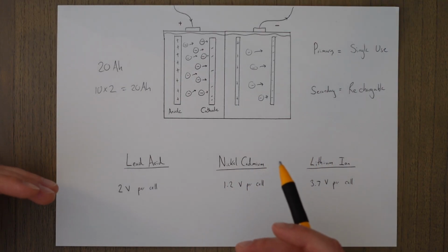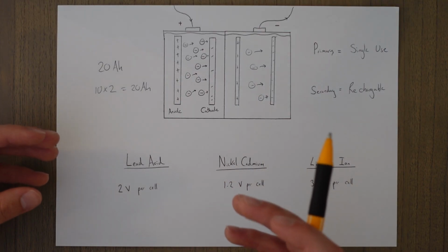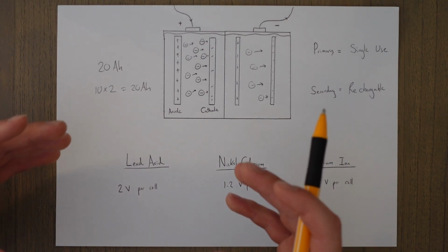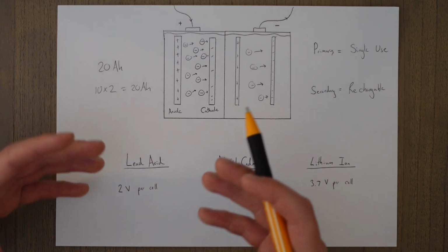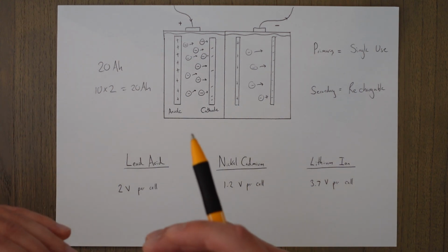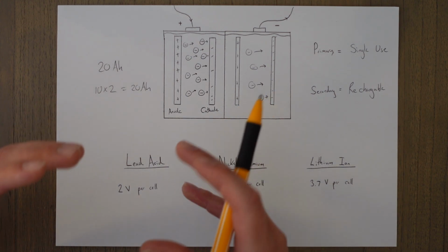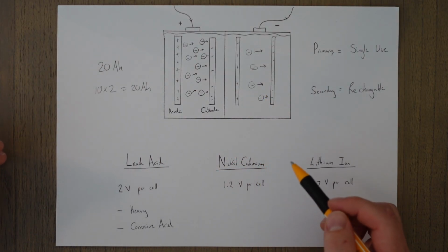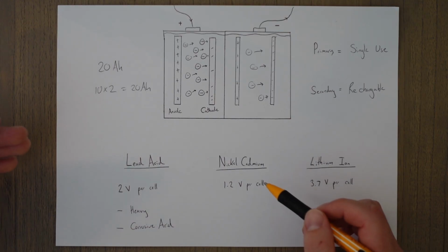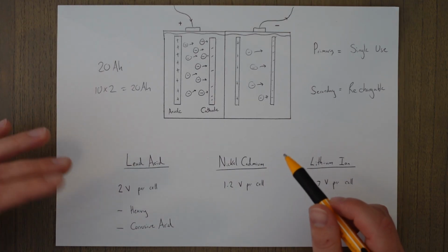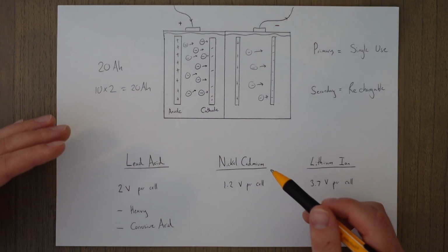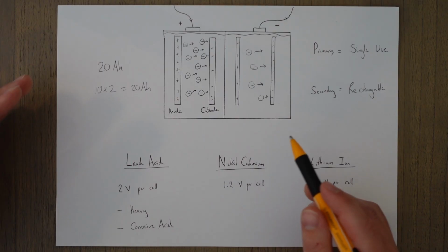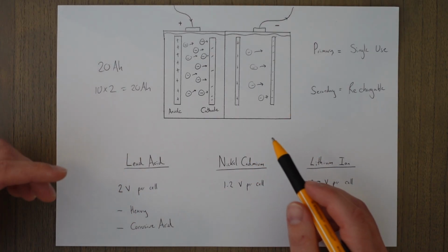However, lead is heavy, and flying around with heavy and highly reactive, unstable acid is not good, especially if it leaks. This can lead to problems with other components potentially reacting with that acid and failing. Because of this, nickel-cadmium batteries were designed. So NiCad batteries, as they're often called, have a nickel and cadmium composite material for one plate and a different nickel composite for the other plate.